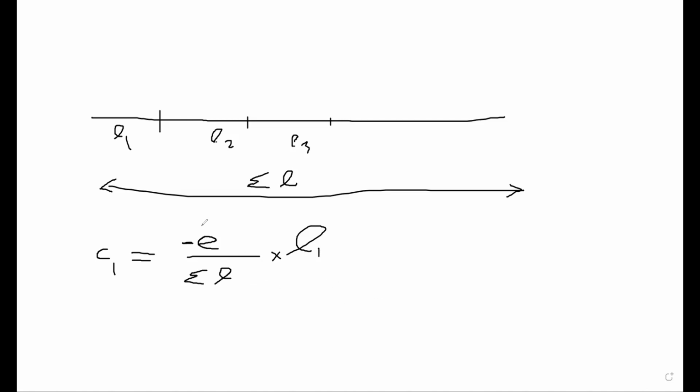So is this calculation clear? So what we do in this case for length AB, if you want to calculate the correction for AB, total correction is 1 millimeter plus 1 millimeter divided by 217 point something multiplied by that particular length of AB.